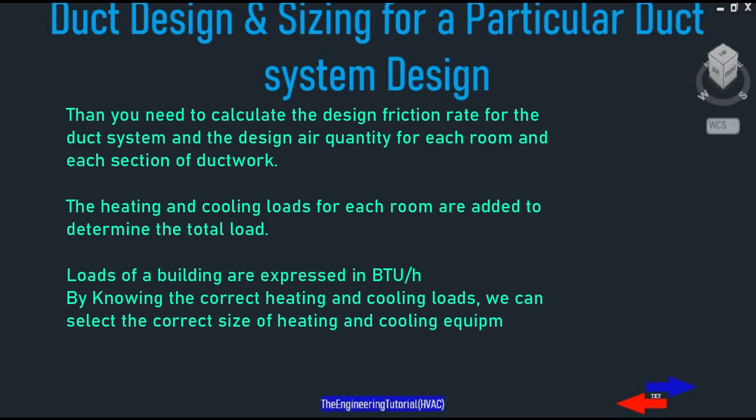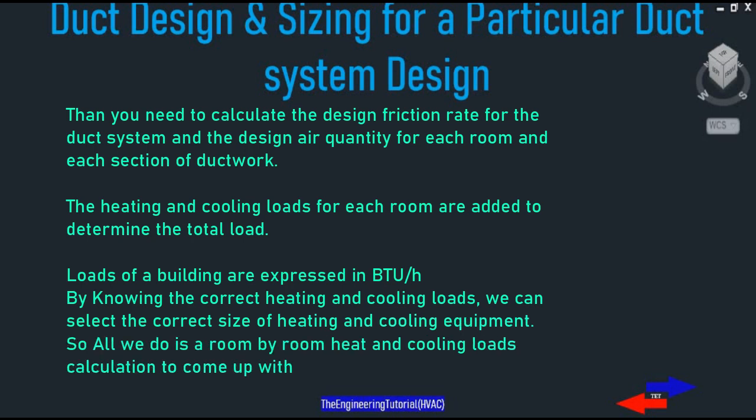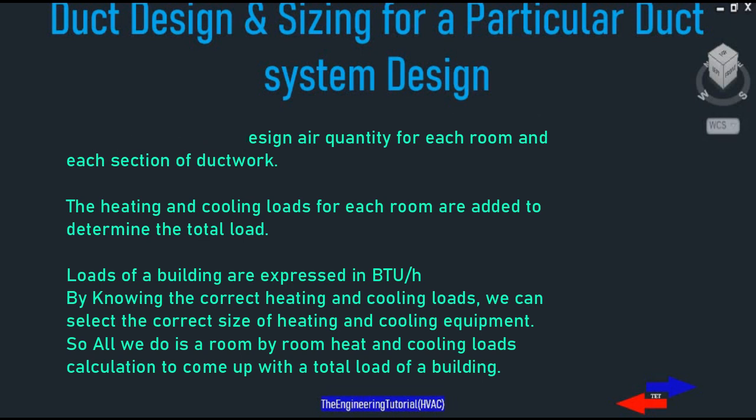The heating and cooling loads for each room are added to determine the total load. So loads of a building are expressed in BTUs per hour. So by knowing the correct heating and cooling loads, we can select the correct size of heating and cooling equipment.